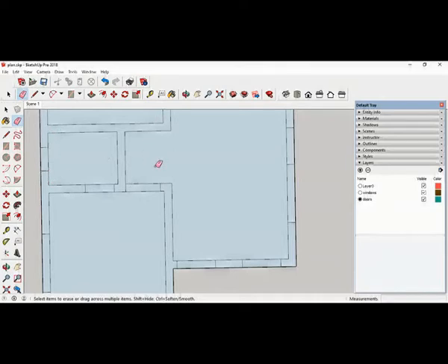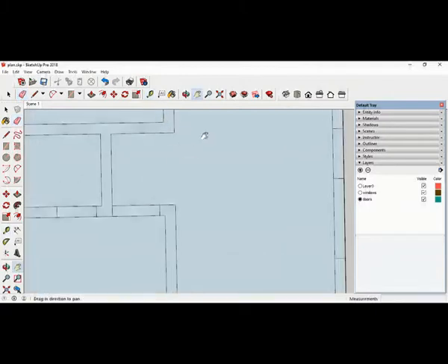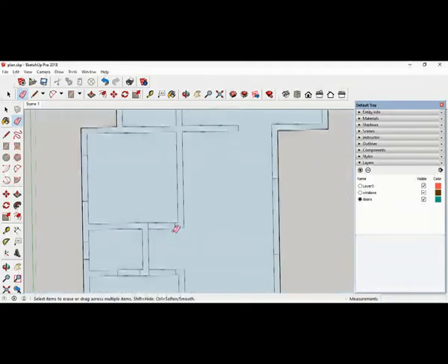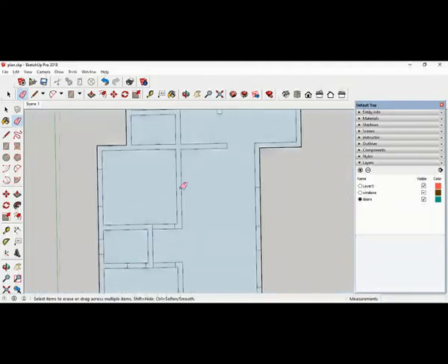Now here also we have to draw. So tape measure tool. 0.1, 0.9, rectangle, erase, just type E, no need of pressing enter or anything. So this is your door opening. So this is for toilet opening for there.